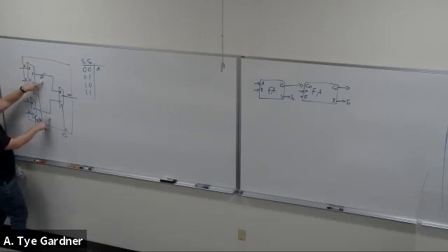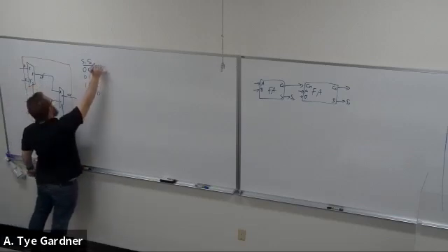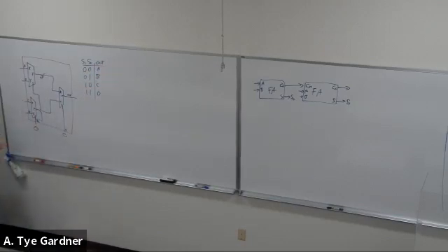B, D appear here, 0 at S1 means I take B. There. I have a 4 input mux, right? Or a 4-to-1 mux is another way of saying that. So I can take 4 different inputs. I have 2 bits to select which one of those 4.